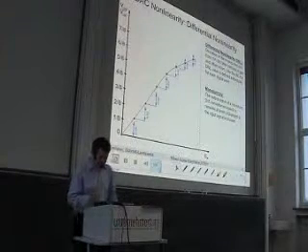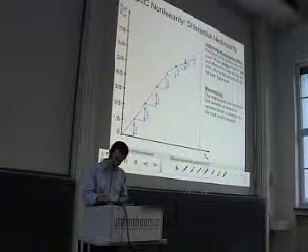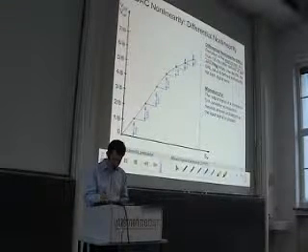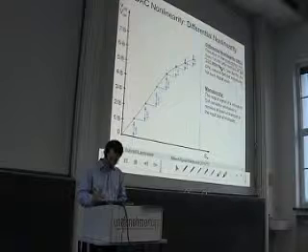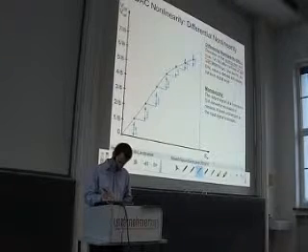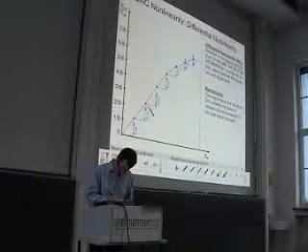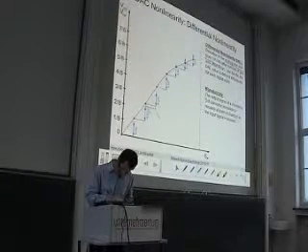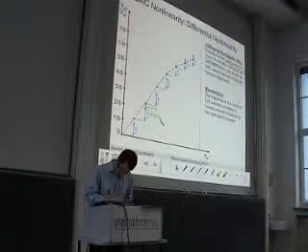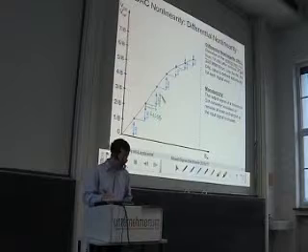So the differential nonlinearity is the deviation of the analog step size from one VLSB. This means if we increase the input by one LSB, so if I go from here to here and say this is plus one LSB, then in the ideal case we should go up by one VLSB.